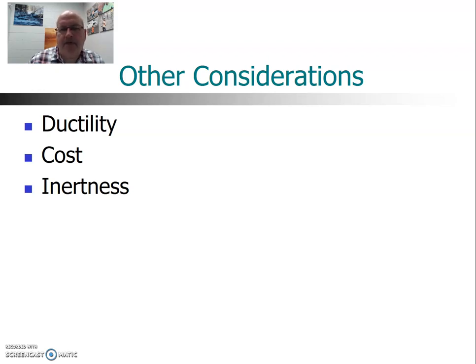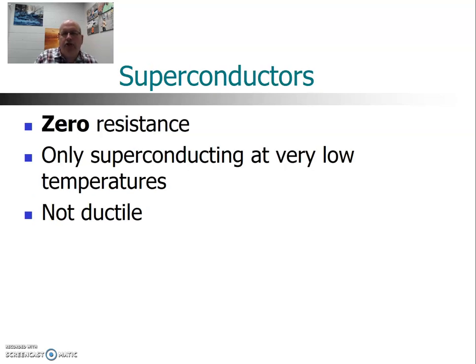That is not because the resistivity is low, but rather because it's very, very inert, so that it will maintain a good connection. It doesn't oxidize and increase in resistance because of the oxidation, so it will be very stable. And I think there's a marketing aspect to that. People associate gold with high quality. It's high cost, and a lot of people think, well, if it costs more, it must be better. But again, it has a use for contacts and connectors and so forth, but is not really the best conductor.